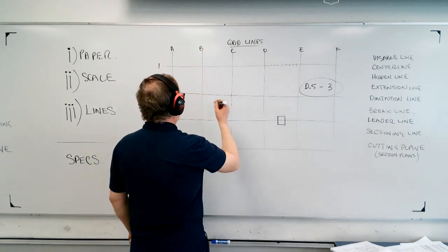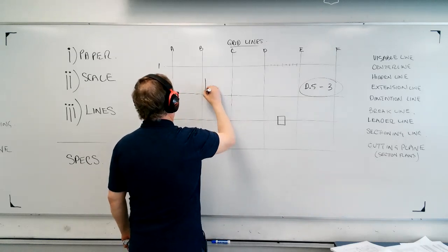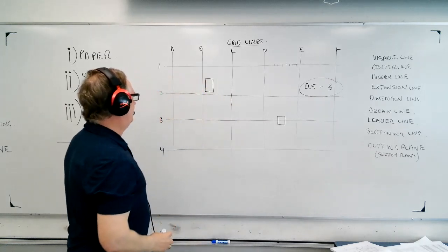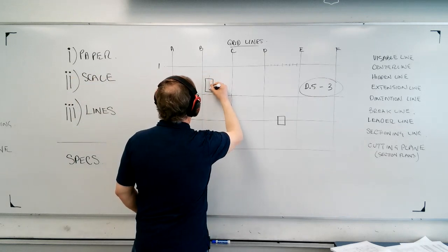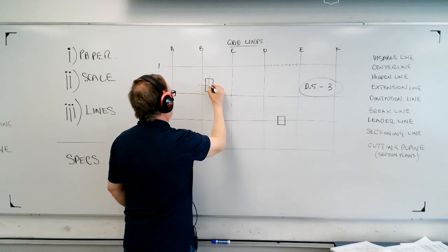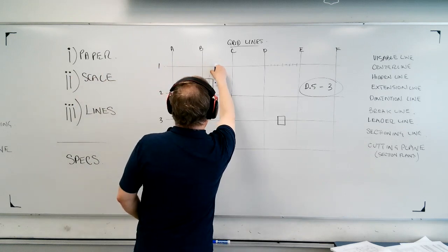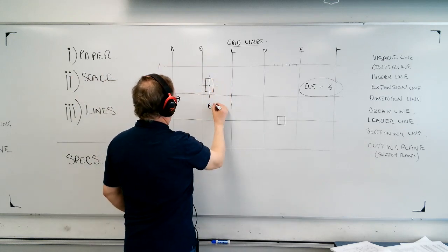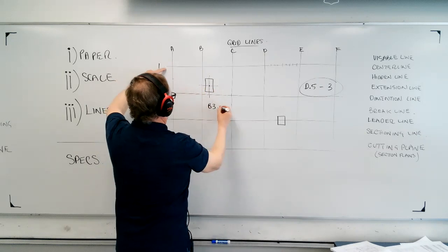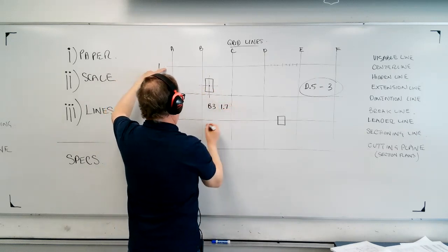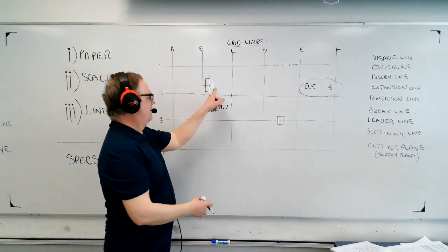And so I'll just give you a couple more. What if I put some random thing about here, okay? And I go, where is the center of this panel actually on the plan, right? So I go like this. Well, that's about the center, and that's about the center. So I'm going to say that's the center point. And now I'm going to go, well, that's at about B. I'm going to say B3. I'll be really close, right? B3 and 1.5. I'm going to say 1.7. Okay, B3 and 1.7. And those are sort of the grid coordinates of where that thing is.